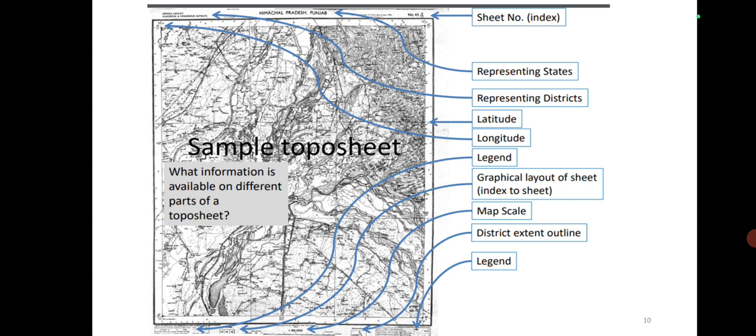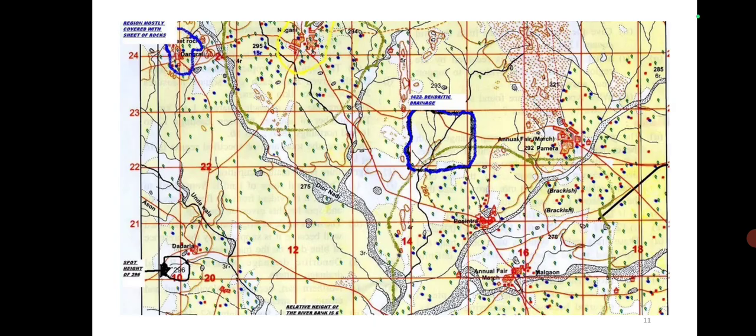Okay. So the Government of India has adopted the metric system for all measurements, and all the maps issued by Survey of India were drawn to a scale of 1 in 50,000, 1:50,000. In the system, the survey territory is divided into 100 km by 100 km squares, and each square is denoted by an English alphabet. So this system of mapping is called the National Grid Reference. So here you can see the grids, the different grids. Okay, and this we call the National Grid Reference.